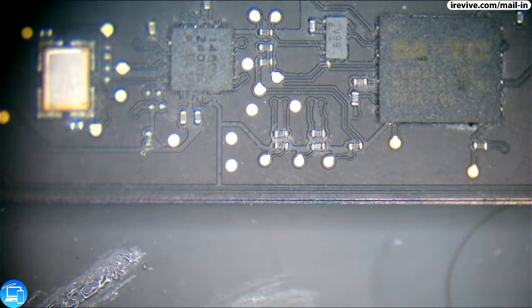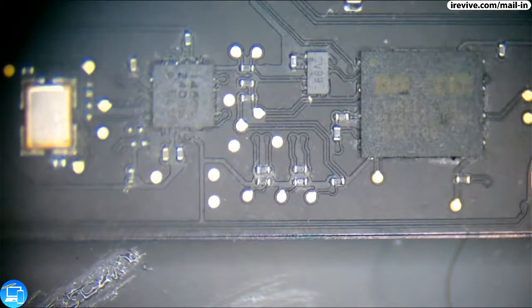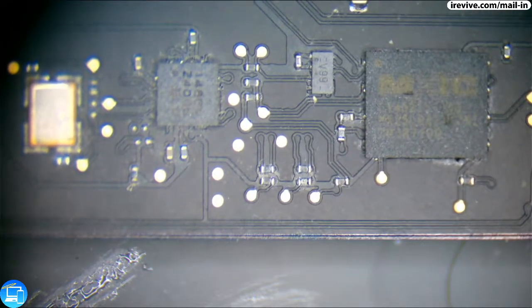How's U5000? I was just about to check that because if we're not going into an S4 state, feel like the 5.5. Oh wait, U5000, my bad. That is going to be the SMC. I'll take a look at that here in 1 second.